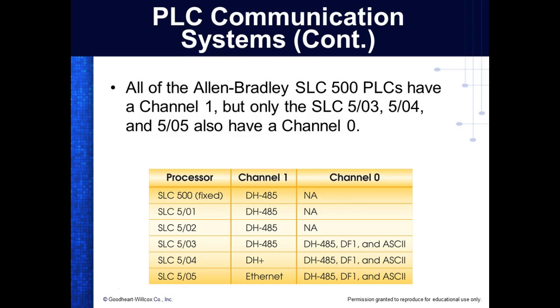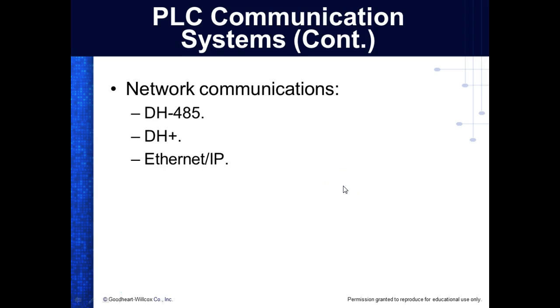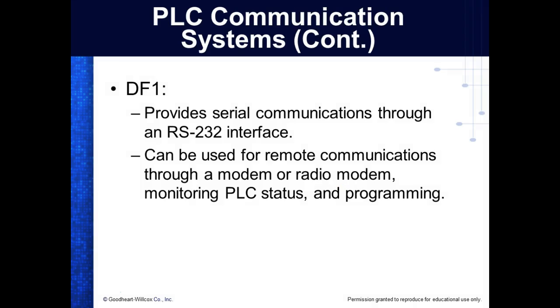You understand that? This guy right here has been around for years. Even the brand new Allen-Bradley PLC still supports this 485 interface right here. But now most of their PLCs have an Ethernet interface on it too. But Ethernet is a little more complicated, and I'll show y'all that on the 1100s. And so the RS-232 interface, with anything, y'all.